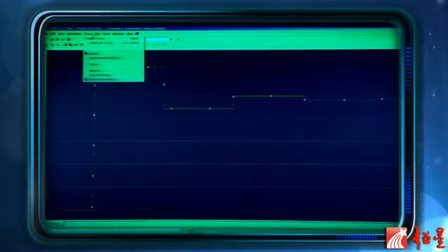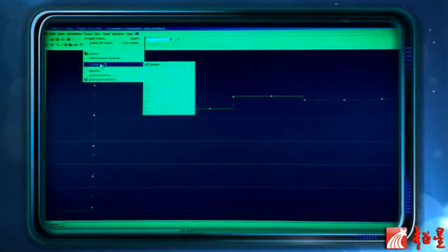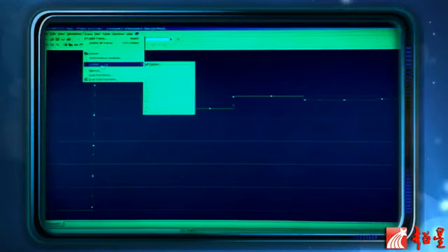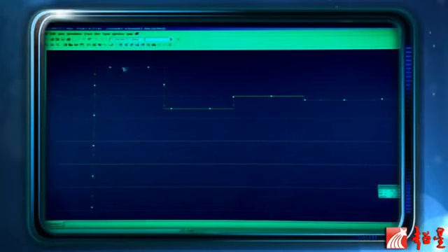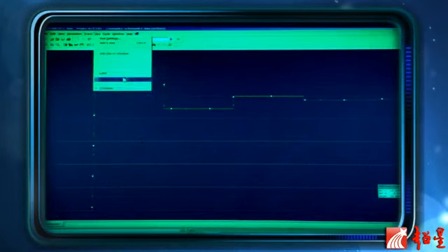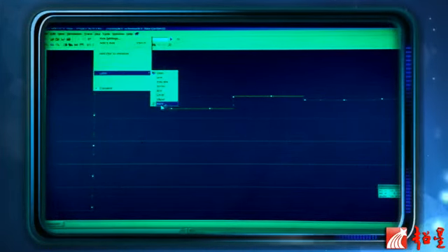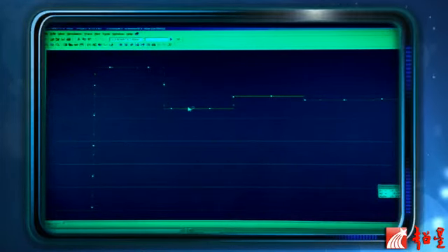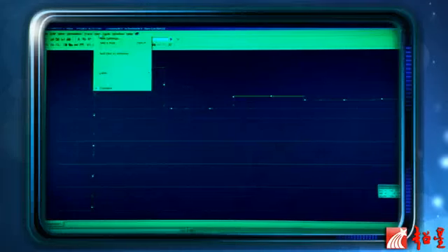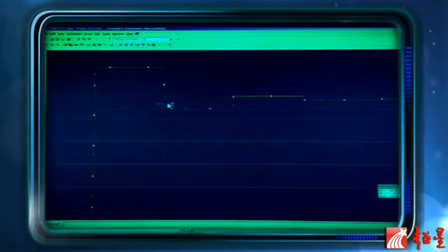You can go to trace and then cursor, then say display, and then go to plot, labels, and then mark. Then you go to the next location and go to plot, mark.